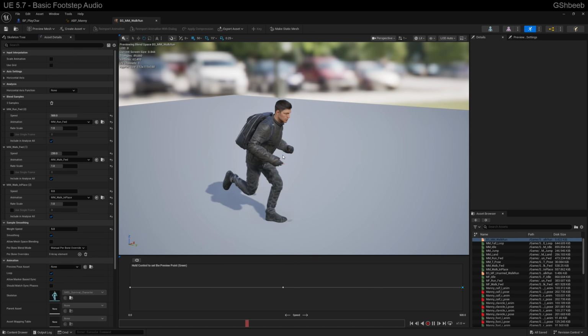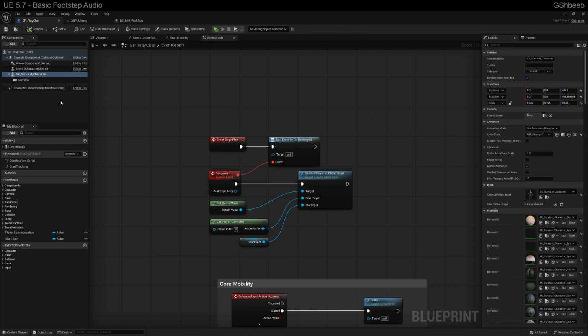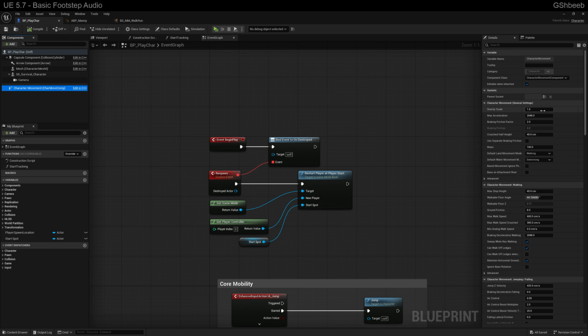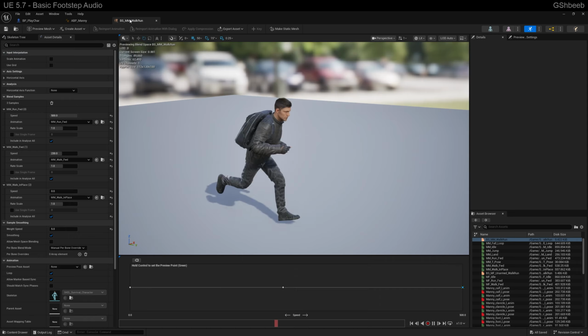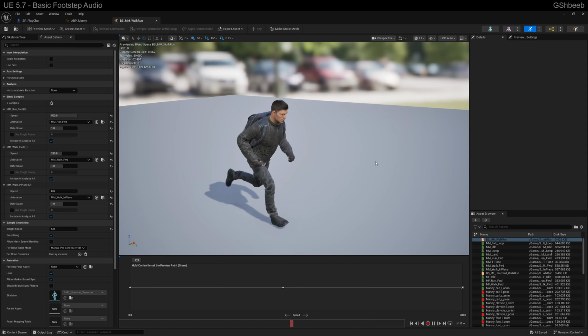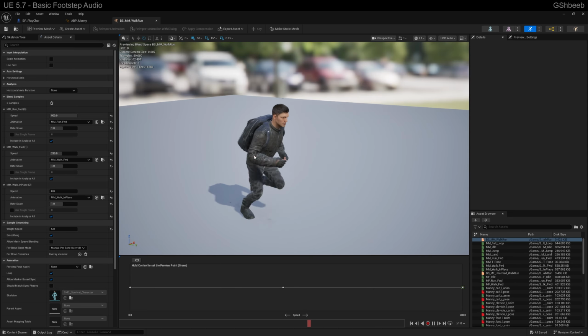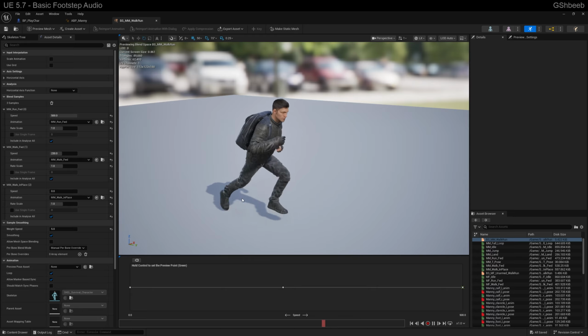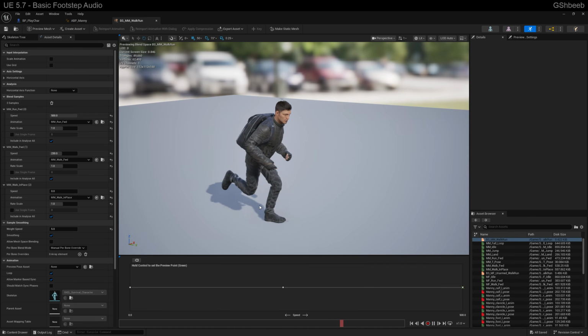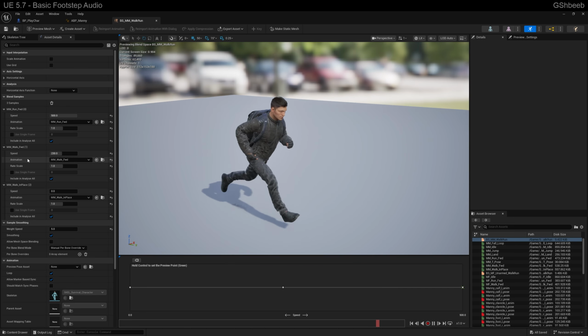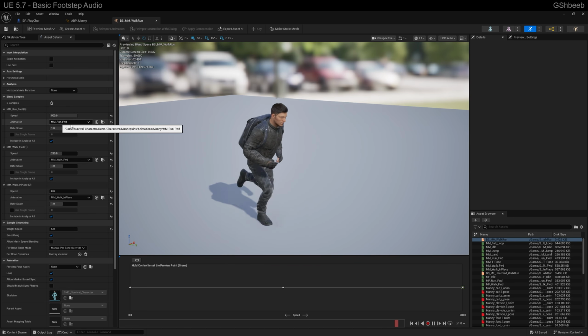And we know that the default character setup for our player character uses the character movement, which has the default land speed of 600 units per second. So the max walk speed is going to be over that threshold, which means at 500, it's going to be running this animation. And so we know this is the animation that we're going to want to use if we're playing mouse keyboard. If you're going to be using a joystick or enabling a walk function, then you can start to target the other animations. But for us, we're just going to run through on the run animation.